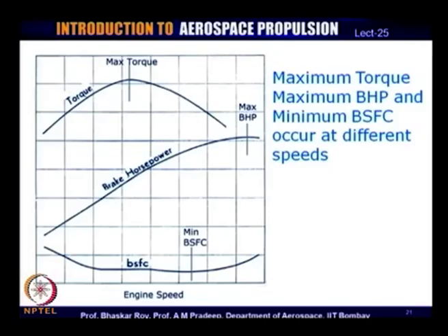Typically, he would like to do it in such a manner that, taken over the entire aircraft flight, let us say from takeoff to cruise to landing, finally the total fuel consumption would be at a low value. So, this requires a certain amount of engine control and propeller control, a little bit of which we might discuss later on in this course. And the 2 controls together will have to find a balance of using the engine for maximum torque or maximum BHP or minimum BSFC.